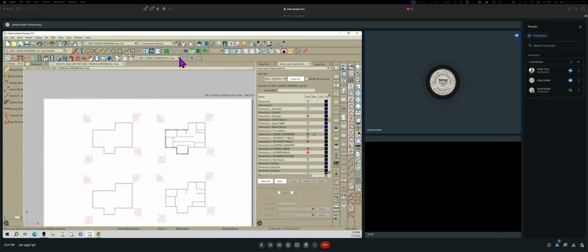here's the thing: when you start putting these on, using the layer sets to control your dimensions, okay? Because when you're designing a home from scratch, you're just starting off. You don't really want all of the dimensions to come on at one time, okay? You just want your overall dimensions. That's all you want to come on when you're first starting out. It's just the overall, to check and make sure that your design is going to fit within the footprint that you're working with on a site plan.